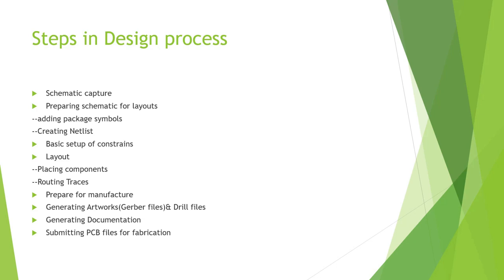We do the placing of the components. Placing is the arrangement of the components, just arranging them properly. If the placing is good, the communication works perfectly and the connections become much easier. Placing is a very important point in layout design. After the placing comes the routing section, where we connect the routes and correct the traces, everything.